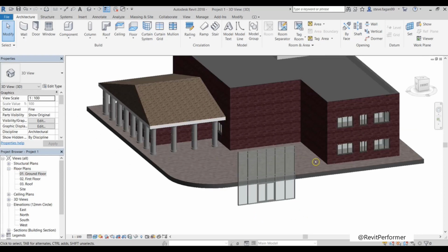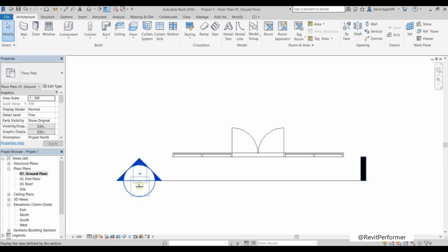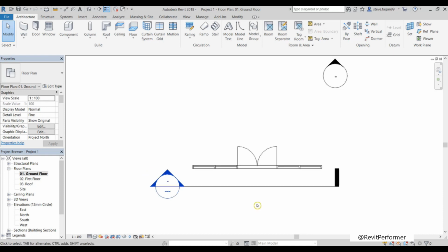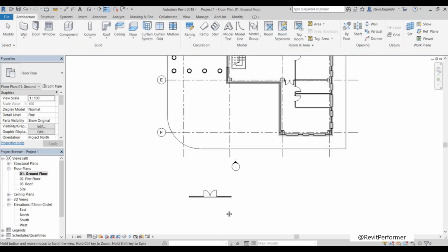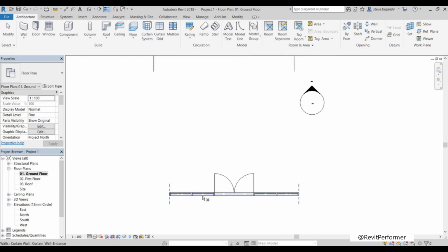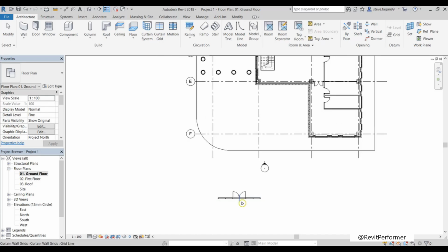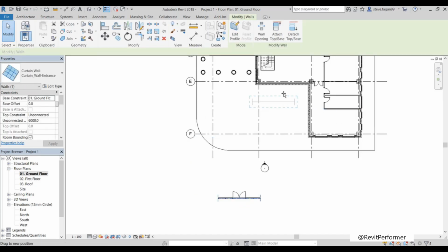So the last thing to do is to just insert it into the building. If you go to PDF 017 curtain walling, you'll see the position of the curtain wall itself. So I'm just going to delete the section view. Again, remembering when we want to move the curtain wall, you've got to look for that H symbol. Click, and that is the curtain wall itself. Then you can click and drag.